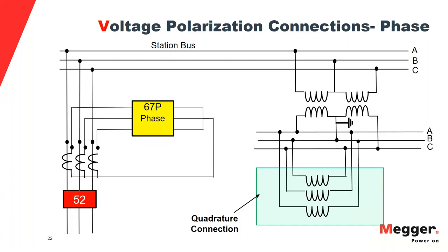In electromechanical relays, the manufacturer uses a capacitor inside to keep the last operated voltage as a memory voltage. That gets changed every time the voltage in the power system changes where the relay is connected. In modern numerical relays, whatever is recorded at the last fault is the memory voltage.